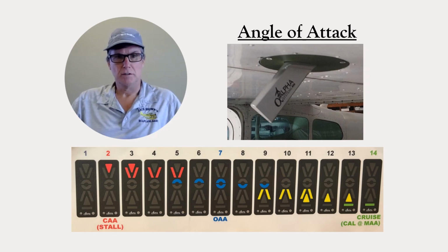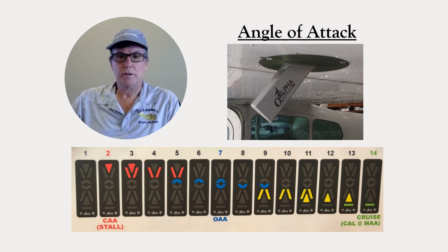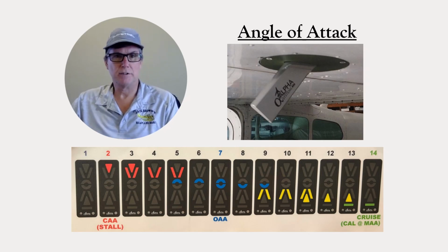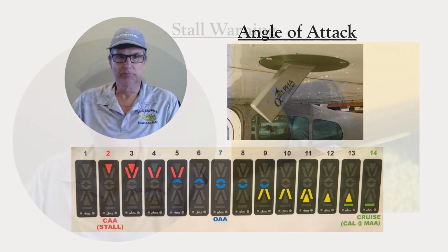That's changing. A number of manufacturers have started to offer retrofits, and new aircraft are starting to come with angle of attack sensors and angle of attack indicators. At this point, there hasn't been any standard that has emerged about how angle of attack information should be displayed to the pilot. The picture below here illustrates one manufacturer's approach to displaying that information.